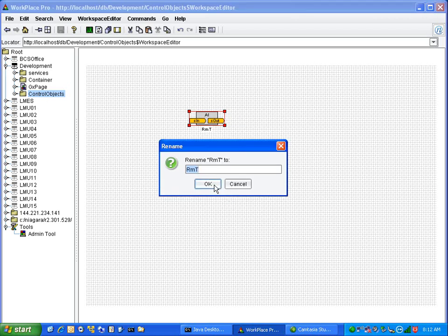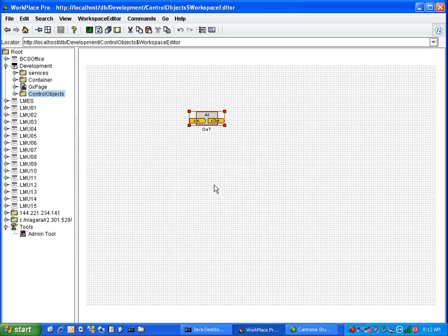You'll see in a lot of my jobs there's always a container I create called global, and within there I'll make an outside air temp tag. I'll use that single point to link the outside air temp from the source UNC to the UNC in the global container that does not have it, and all of a sudden this becomes that UNC's outside air temperature. From within here, I will then link the output of this object to all the other controllers that require outside air temp. I hope that makes sense.